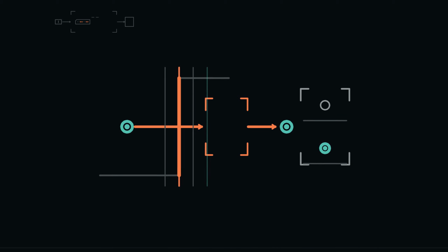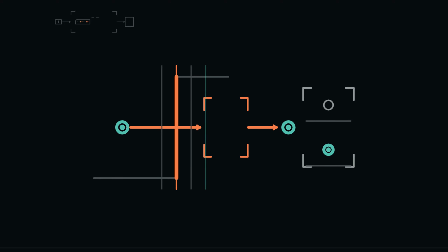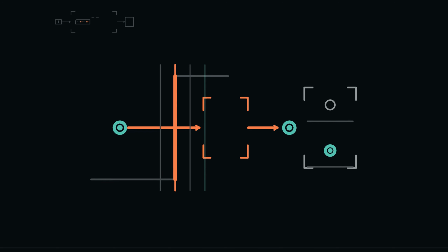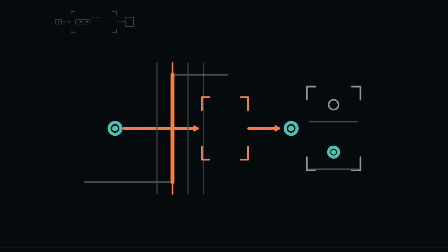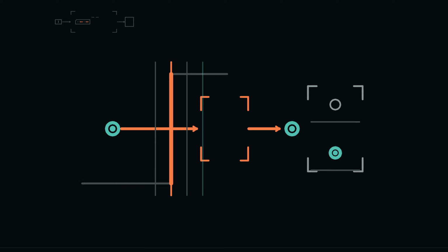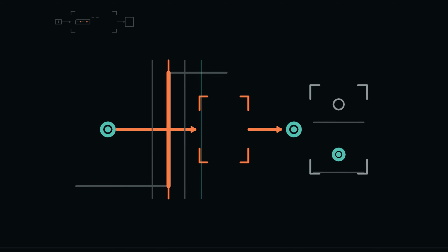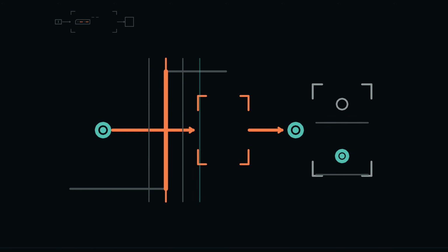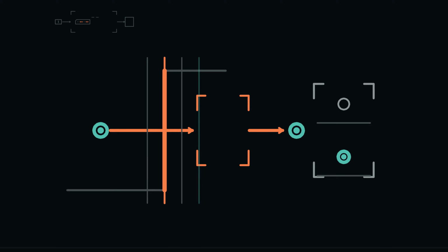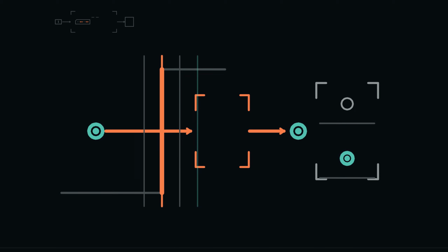Now place two storage elements side by side. Before an edge, each next state input is calculated from the old outputs. At the shared edge, both capture. Only after their propagation delays do the new outputs become available for the following calculation. This lets us reason as if every participating element reads the same old chapter and then turns the page together. The page turn image maps the separation of state generations. It does not claim perfect physical simultaneity across a real chip.